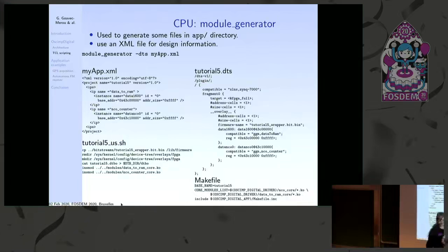First one. Second, the device tree. You need to append, and you find exactly, you append the FPGA full node, a node dedicated to handling the FPGA. You have the firmware name. You have one driver with the same base address, exactly the same. And finally, a makefile. The makefile is just used to cross-compile the application, to compile everything, and to install everything on the board. It's finally all about the ecosystem.